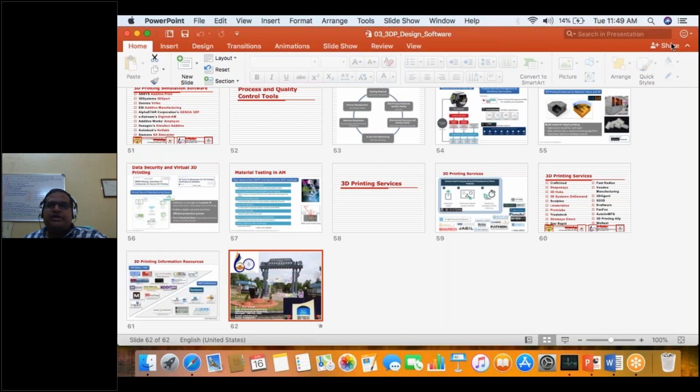That is, we are talking about the repair of the part, right? So yes, repairing or refurbishing of the part is very much done with additive manufacturing processes like DED, and even with some kind of powder bed process it is possible. DED is the right one, but we must have CAD software and you reverse engineer it and superimpose this with the original data and you will get the deviation. So like that you can get a match of 100% or at least 99% with the original geometry, and service parts also we can repair.